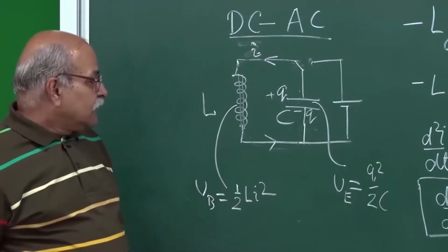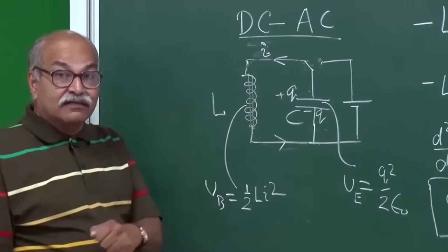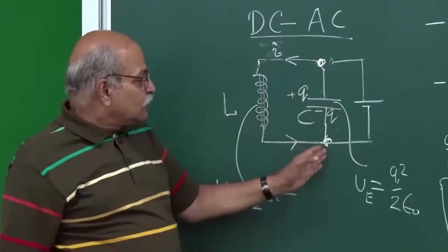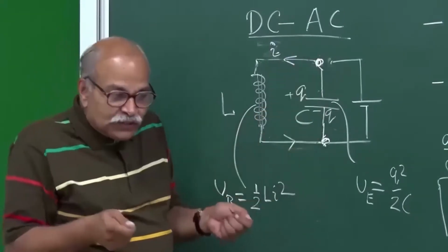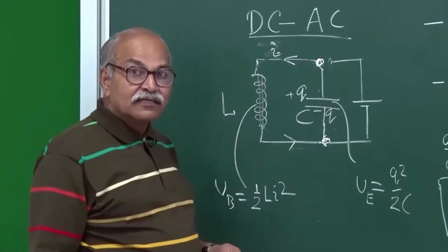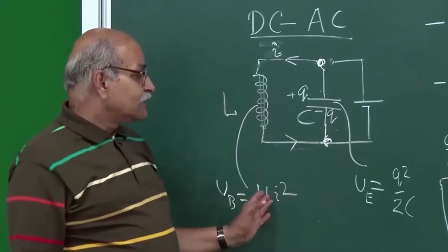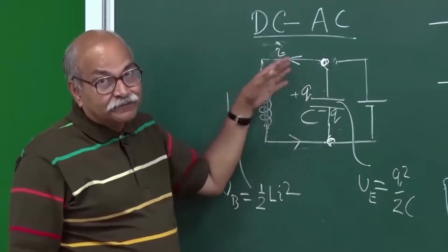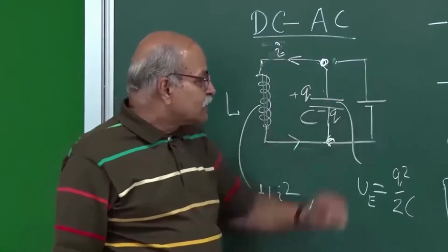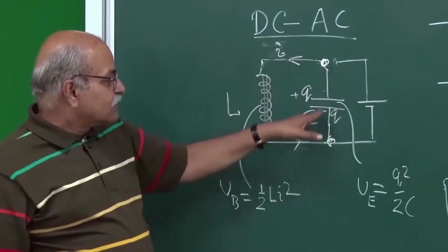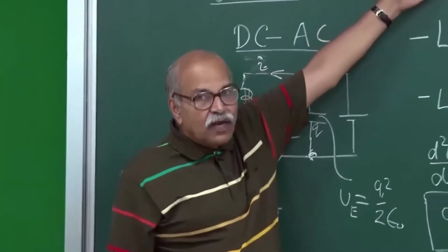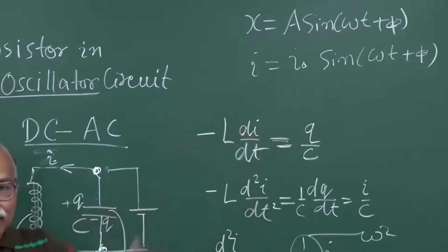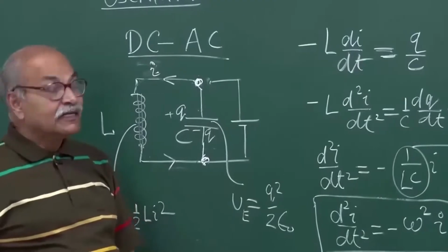But then if you use this in some circuit, if you want to make use of it, you can take any potential here, voltage. This voltage is oscillating in time, so you do have an oscillating voltage. But if you want to use this oscillating voltage for some kind of a circuit, you want to connect it to some external unit, then this energy is not going to remain constant. And if you are using that energy, that means this oscillation will die out. And even if you don't use it for an external purpose, internally it does have some resistance, and then this equation is not going to work, because you have another resistance into I term in the equation, and power is dissipated there, energy is dissipated there.